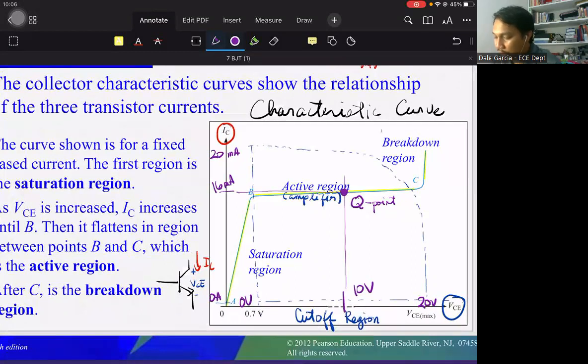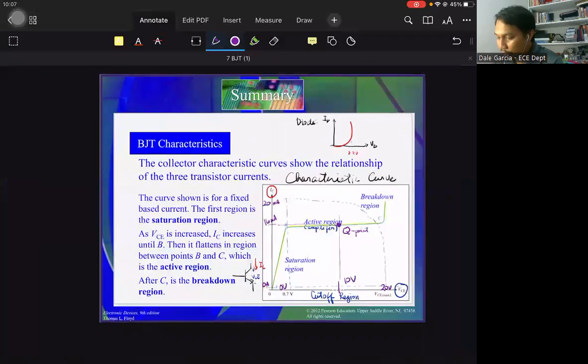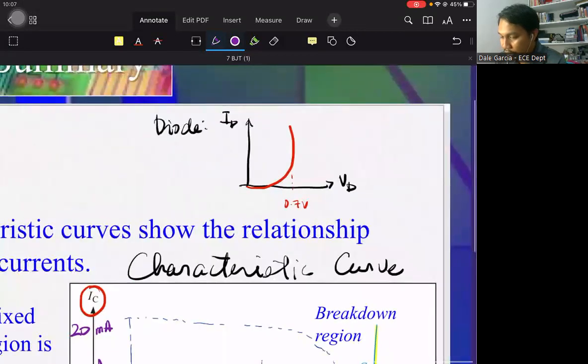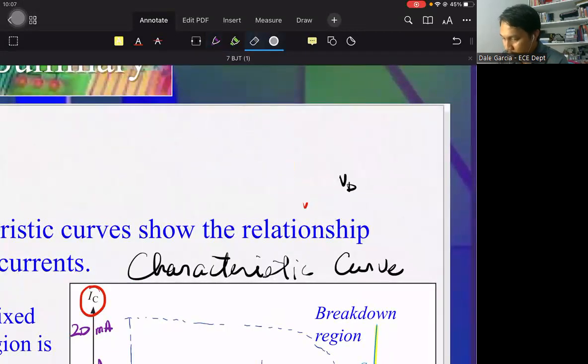The breakdown region is here just to let us know, it's a no-fly zone. Again, if we want our transistor to be used as an amplifier, we should locate our Q point inside the active region. So what if our Q point is in saturation or cutoff? Will the transistor be destroyed? No, it won't. Of course, it only gets destroyed if it is in the breakdown region.